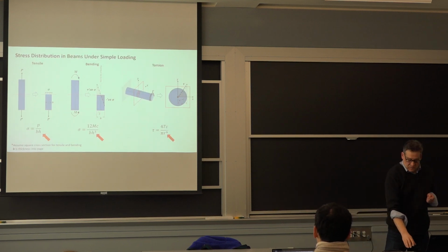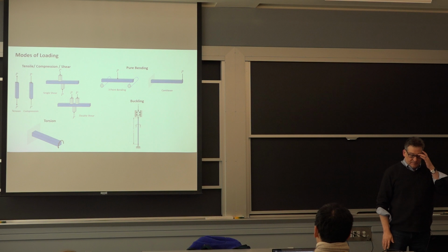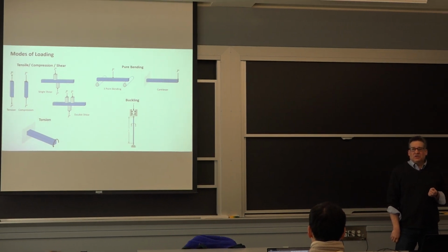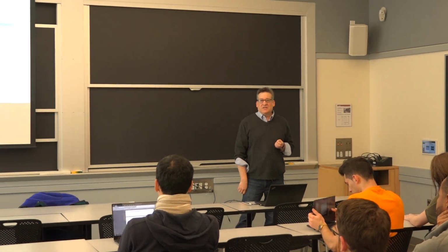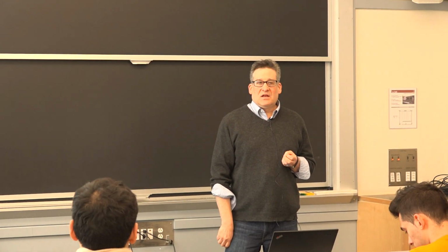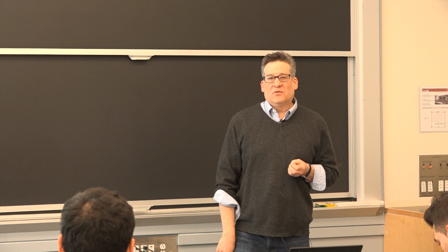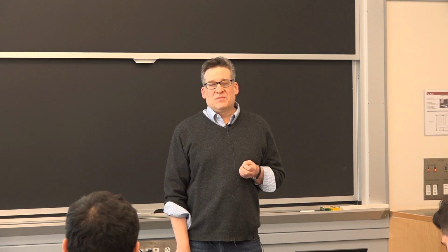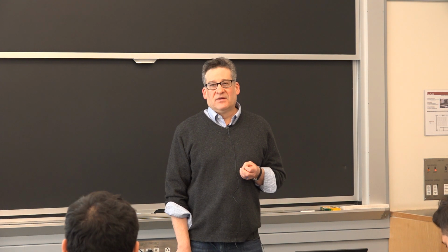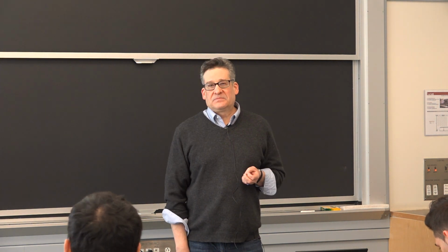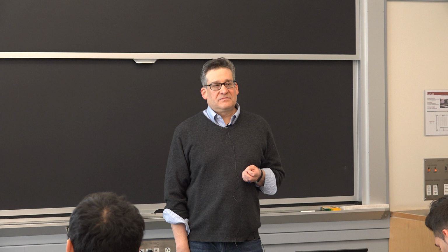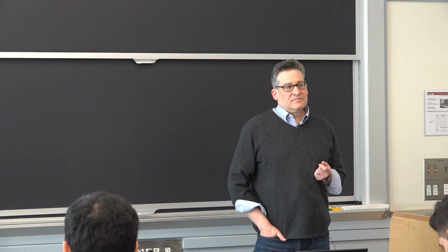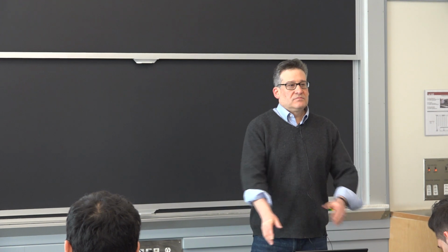Can you explain why double shear is better than single shear? Because double shear reduces the stress at each of the mounts, and it reduces a kind of bending load at a smaller length scale. So you put the material in pure shear rather than some combination of shear and bending. I also think of it as double shear not having a degree of freedom of rotation of the whole beam, right, like the hand of a clock going around.